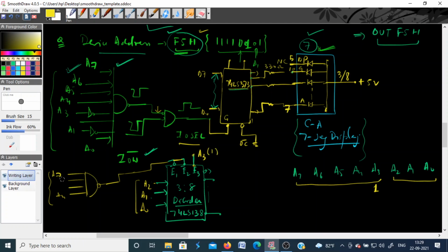So this pin now is fixed to logic 1. Similarly, these 4 address lines A4 to A7 I have combined using a NAND gate to generate an enable signal which is logic 0, and I have connected it to both these enable pins. It means this should be logic 0 when all the pins are at logic 1. Okay, it means also I have set now these to 1 1 1 1. These are fixed, so they are connected to plus 5 volt power supply permanently, right? So all the 5 address lines A3 to A7 are now fixed to plus 5 volt. Now what you are left with is A0, A1, A2.